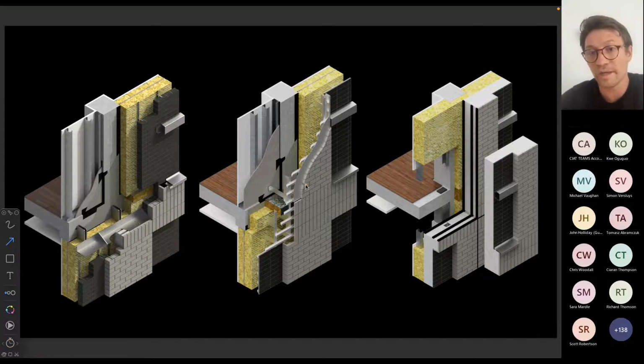backing surface. Whereas the brick slip is more of a rain screen cladding. It is a rain screen cladding. It mostly has hat brackets, rails, counter rails, and brick slips fixed to this assembly. Precast concrete assembly has the brick slips cast into the precast concrete panels, and these are installed on the primary framework.